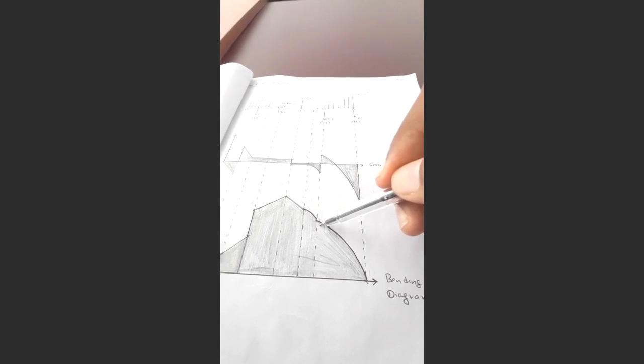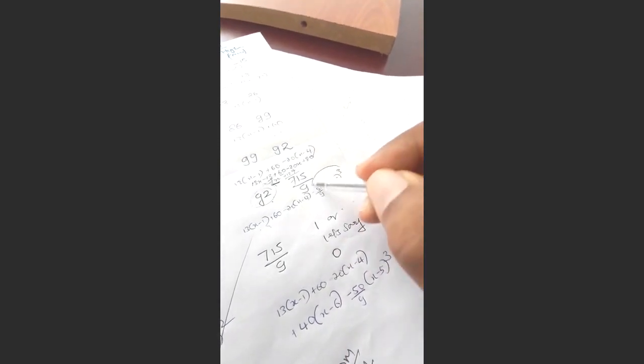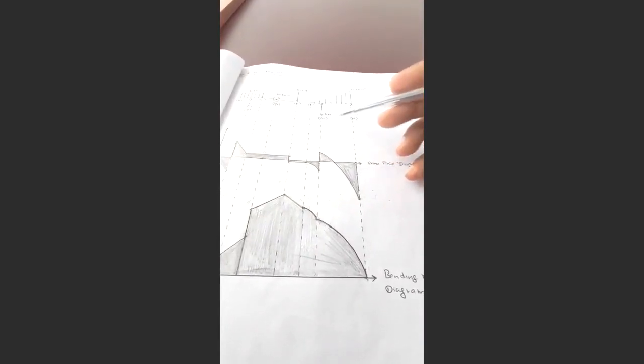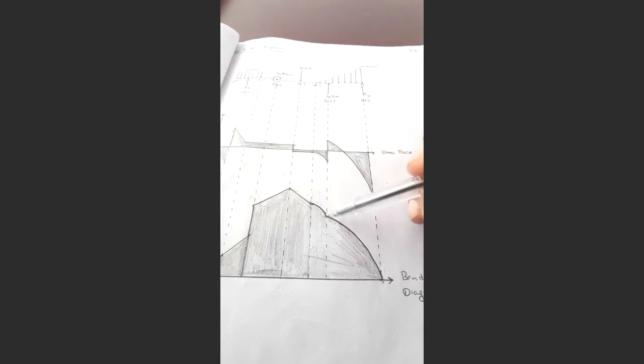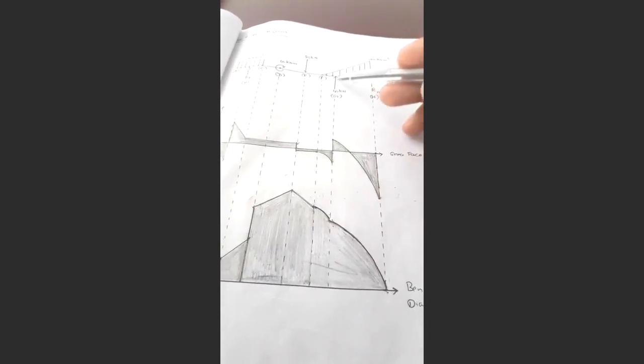So what is the curve type? Is this first order, second order? No, it's a third order, because you have this x minus 5 to the power cube, right? But again, now look at the intensity. The intensity is increasing, so from here to here it's an increasing type of curve. The bending moment is also increasing from F to G. The load intensity is increasing.